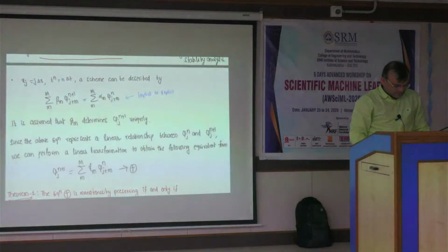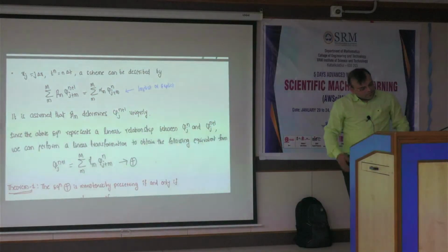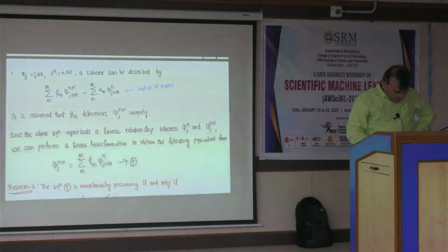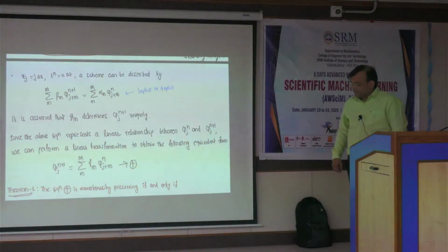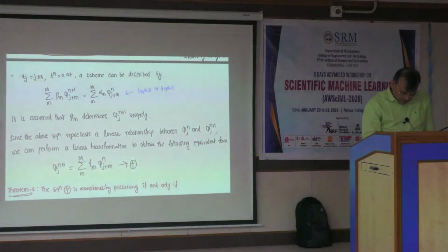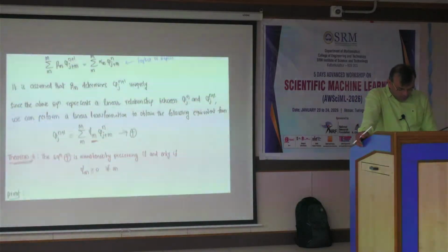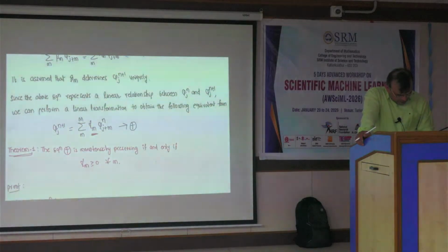So far we discussed everything about the linear advection equation. Now we would like to build second order schemes, and see where this is going wrong and why. The first thing is whether these assigned coefficients are positive or not, that is monotonicity: either it is an increasing or decreasing function. So why are we looking at increasing and decreasing functions, and what is the importance here? I'll come back to this a little bit later.